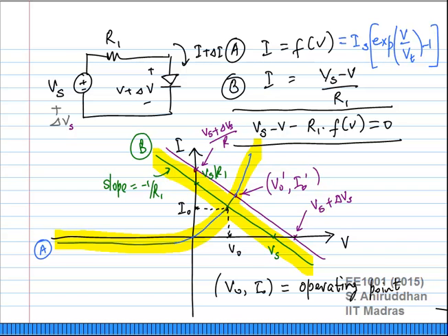The reason is very simple. If you want to solve a linear network, you write down the set of voltages and currents, the relationships using KVL, KCL, and elemental relationships. You can write it in matrix form, invert the matrix, and get it very easily through simulation. It's very fast also. If you need to solve the nonlinear equations, it's much slower. Even in simulation, it's significantly slower than solving a set of linear equations. That is the reason why you want to figure out how to make this circuit simpler, both for hand calculations as well as for simulations.